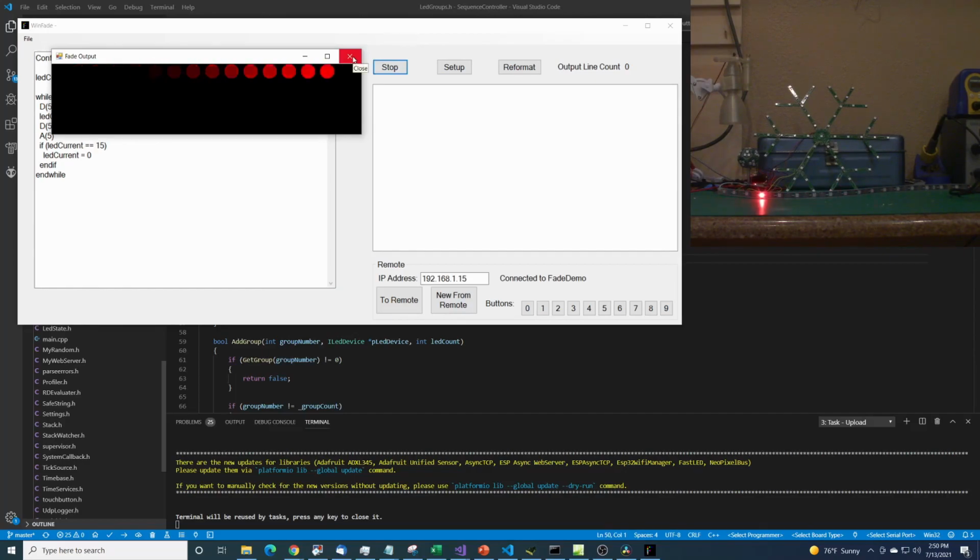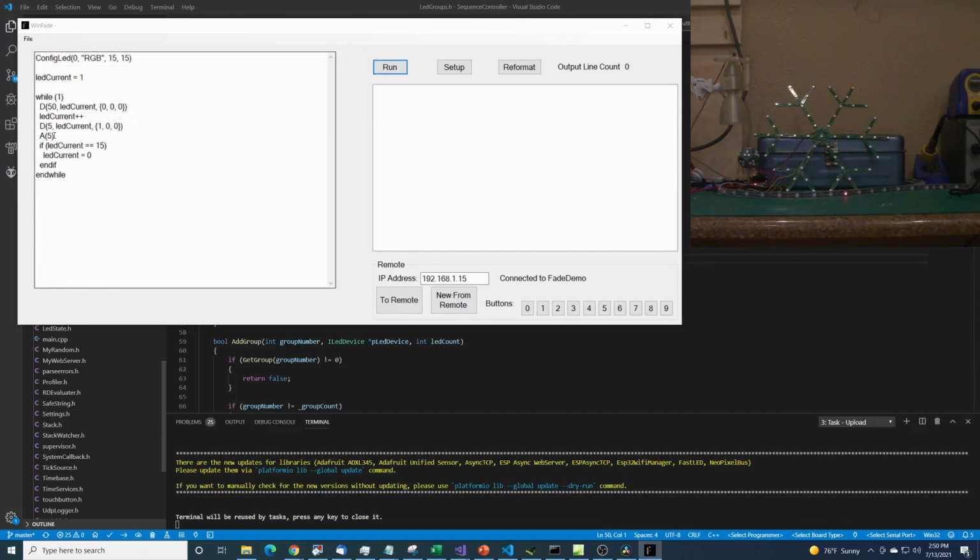So this is very nice. It's a little weird to think about because of the way the loop's structured. We set this dim to happen over 50 clock cycles, but we're only animating here 5 clock cycles at a time. So we set up this one to dim over 50, this one to get bright over 5, and we only animate 5. So this one dims the first chunk. It does the first 5 of that 50. So obviously that doesn't dim it all the way. So that's how we get that trail there.